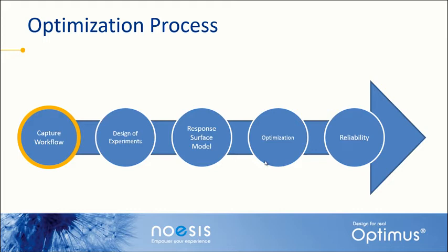After the design space has been sampled with the DOE, we're ready to create a response surface model. This is the surrogate model that we were talking about before. When the response surface model has been generated, a global optimization can take place very quickly on that response surface model. In fact, I believe in our case we ran about 5,000 experiments in about a second. After we've selected our optimum and validated it, we can then conduct a reliability optimization to ensure that we have a stable solution.